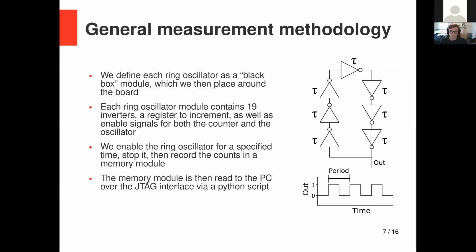So we essentially read out that value of the ring oscillator while we increment a counter up from that ring oscillator for a certain known number of clocks. Our control clock is about 200 megahertz. So we say wait a certain number of clocks, we know how many seconds that was, and then we can say, okay, that was then the frequency of our ring oscillator.